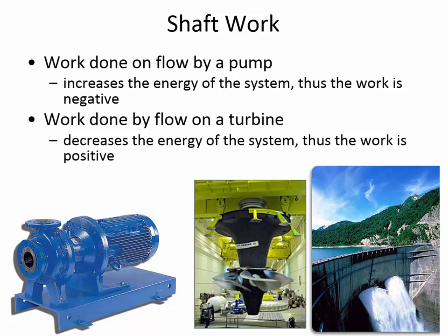And the way that I can explain that is, think about just upstream and just downstream of the pump. If this is location 1 and this is location 2, consider the three terms in the energy equation. There's P1 over gamma plus Z1 plus V1 squared divided by 2g. That's the energy at 1. And then the energy at 2 is going to be P2 divided by gamma plus Z2 plus V2 squared divided by 2g. All right. So how does the pump add energy?